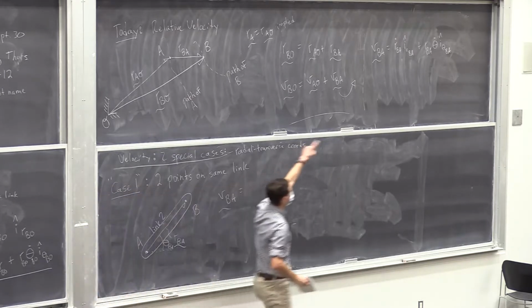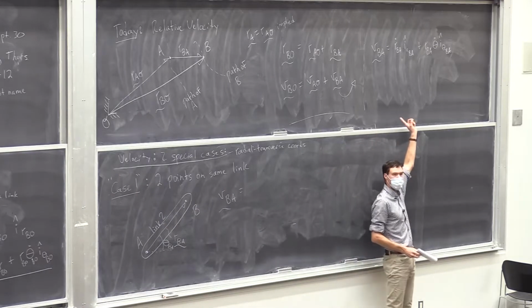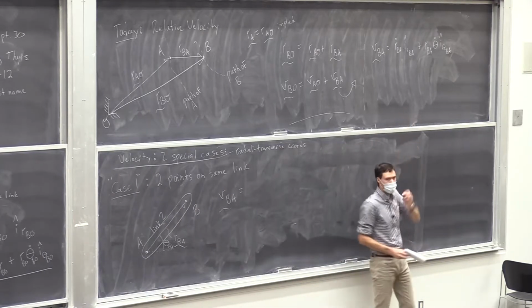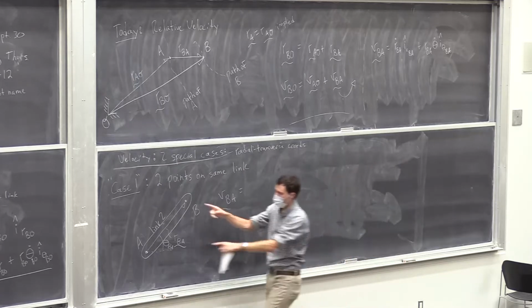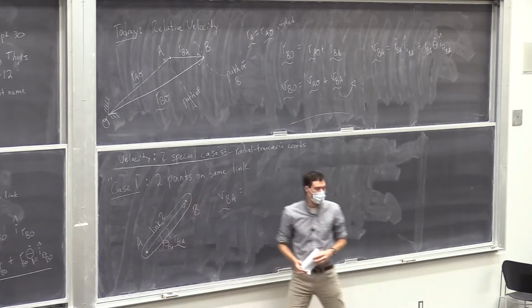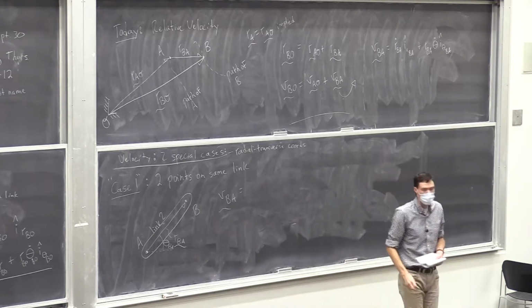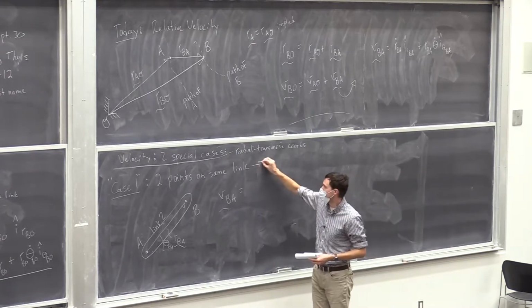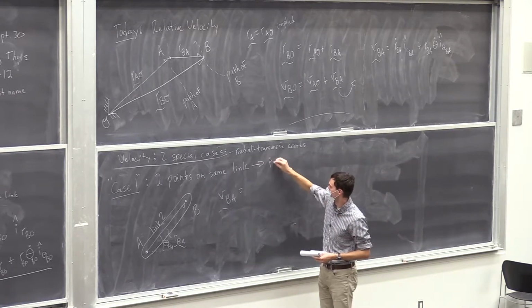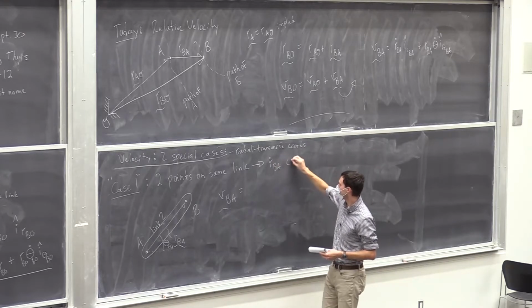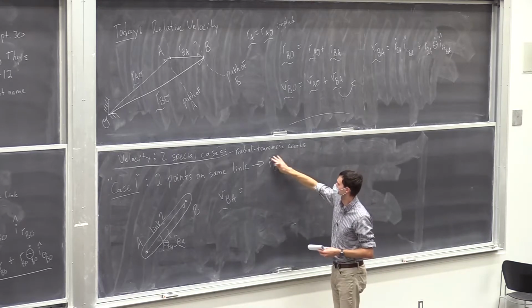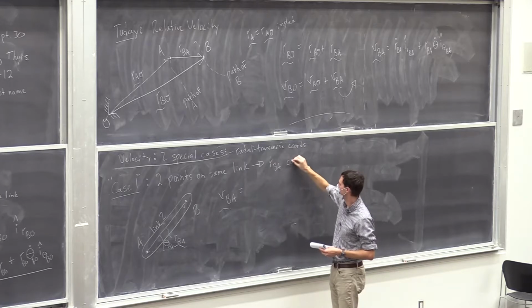Okay, so looking at our equation closely, r dot, it's a scalar quantity, r dot BA. That's the rate of change of the lengthening of this vector. But if these 2 points are on the same link, and it's a rigid link, that tells us that the length is constant. So r is constant.